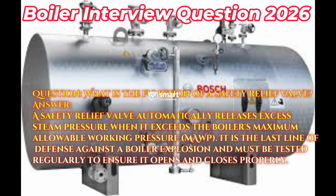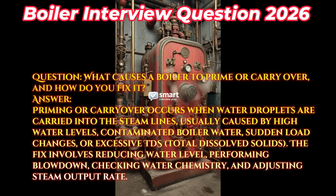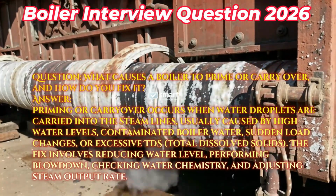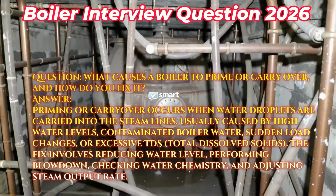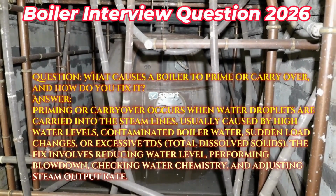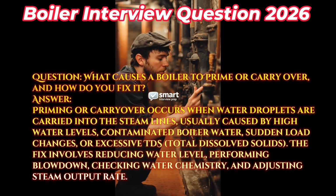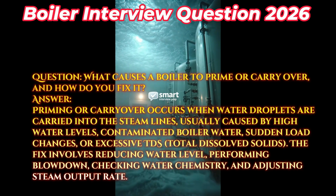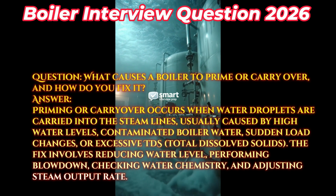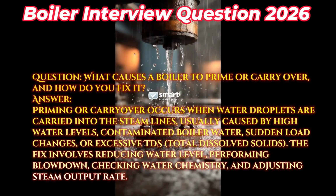and closes properly. Question: What causes a boiler to prime or carry over, and how do you fix it? Answer: Priming or carryover occurs when water droplets are carried into the steam lines, usually caused by high water levels, contaminated boiler water, sudden load changes, or excessive TDS, total dissolved solids. The fix involves reducing water level, performing blowdown, checking water chemistry, and adjusting steam output rate.